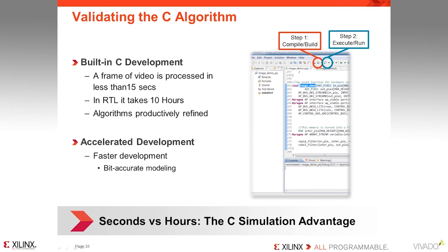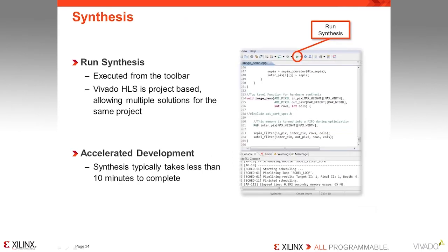Okay. The next thing Vivado HLS does is synthesis. Synthesis can easily be executed from the GUI toolbar, and we'll show an example of this shortly when we go through a small demo. Synthesis from C typically takes 10 minutes. Vivado HLS is never the bottleneck in any design process. You'll typically find that the slowdown comes when we get down to RTL synthesis.